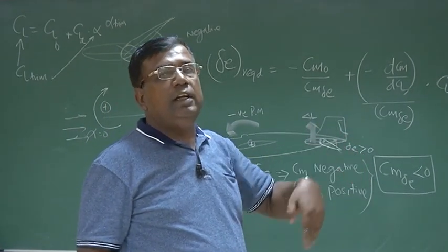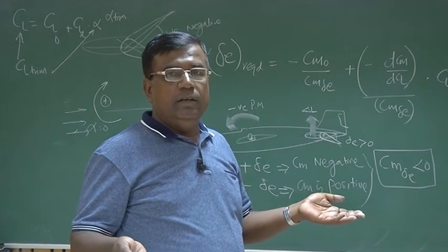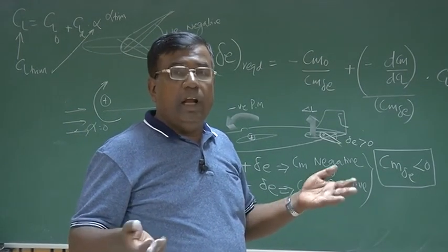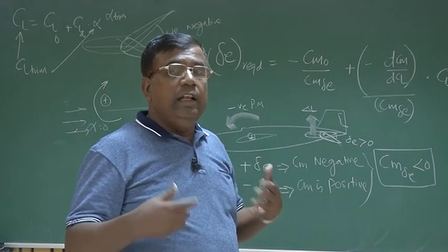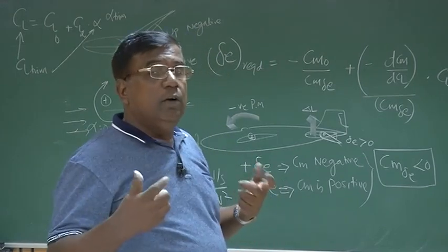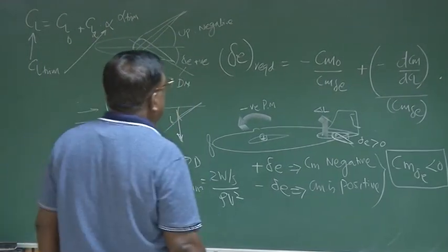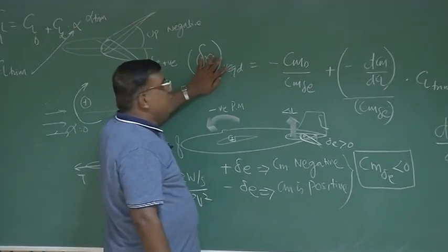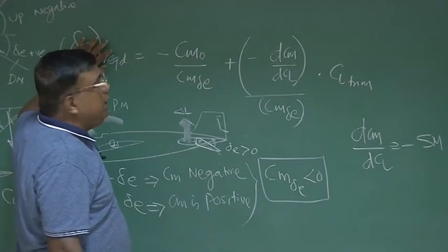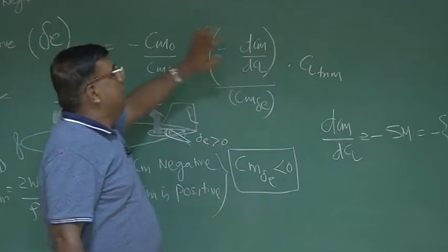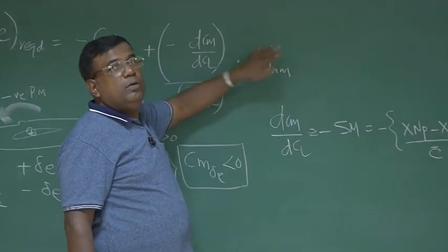So it will not generate lift at all, or very small lift, and more drag, because the flow gets separated. So that is the point where you say the elevator is not effective. So we need to constrain this. You say, oh dear friend, I have a limitation, so I can only control it to my best strength. So it cannot be any CL trim, it has to be a limited CL trim.